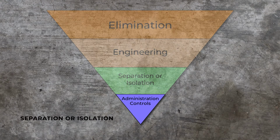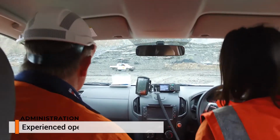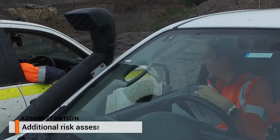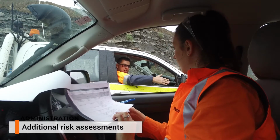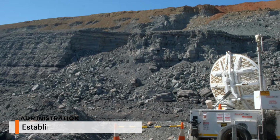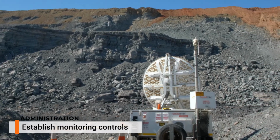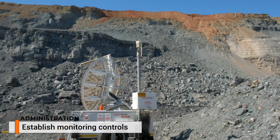Administration controls. Increasing the frequency of inspections, allowing only experienced operators within the hazard zone. Completing additional risk assessments for specific mining sequences, such as mining on retreat or backfilling after mining coal. Establishing monitoring controls, such as peg telltales, wireline extensometers, prisms, LiDAR or slope monitoring radars.